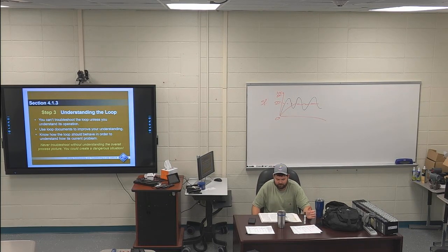There are a lot of different methods of troubleshooting, but I will say this: if you have a loop, start at one end or the other. Don't start at the middle and try to guess your way through what's going on. Usually, always starting at the beginning and making sure stuff has power, that was usually 60% of the problem.